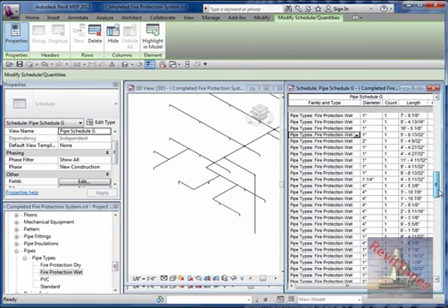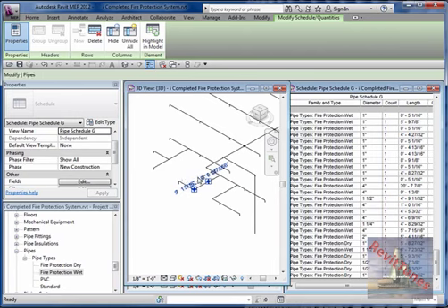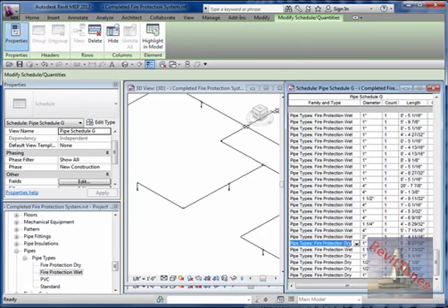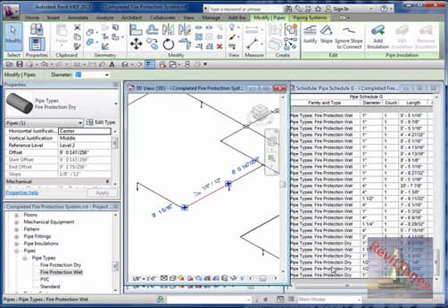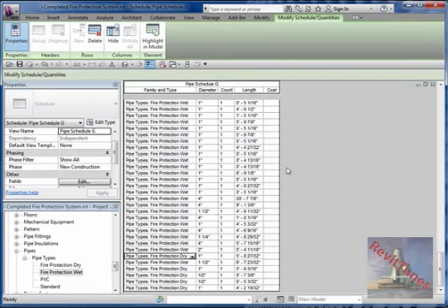Okay, I fixed all those pieces. When I drew it, I grabbed the generic pipe; I wasn't using the default, the wet pipe, fire protection wet system. Now we know we fixed all the dry ones. Let me see, yeah, I could see it here. All these dry are correct. Dry is this, yeah, okay. So now we know we could continue. We know we fixed our error.